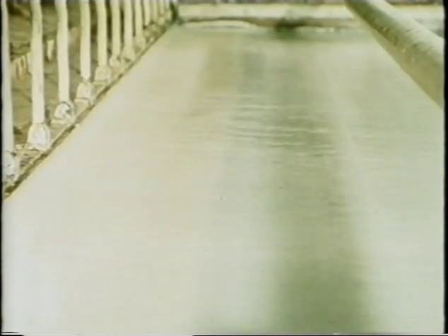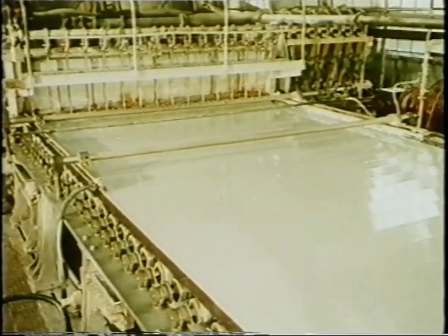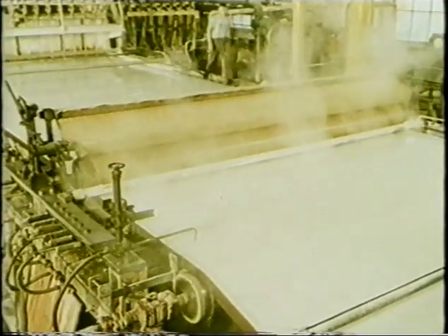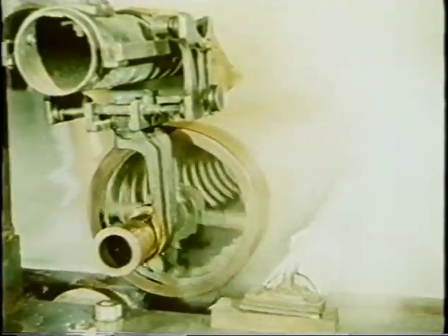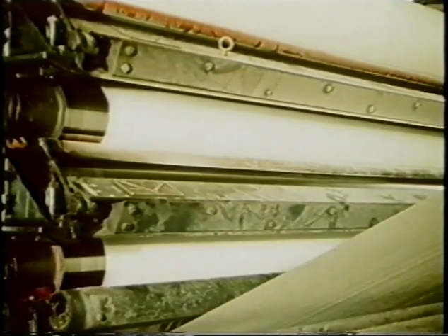The mix is refined, screened and diluted, and then launched onto a continuous wire cloth. As the wire carries it forward, the water drains out, leaving a web of interlaced cellulose fibers. The fiber sheet passes under a dandy roll, which applies the watermark. When the pulp is strong enough to support its own weight, it leaves the wire cloth. It is now paper. After drying, it passes over calendar stacks, which gives it its glazed finish.